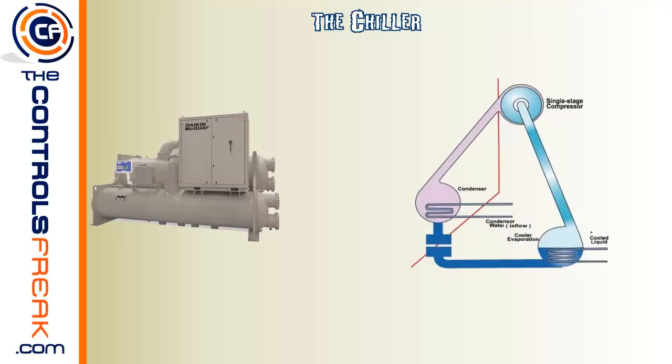One other thing to note about chillers is that in these barrels that you see here, there are many different bolts that come across here that seal up the 2 ends of this barrel. Inside the main portion of this barrel, these water lines that you see here are actually long tubes that run the full length of the barrels. And so if you ever hear somebody saying they were changing out tubes or they have dead tubes in the barrels and so forth, these are the many tubes.